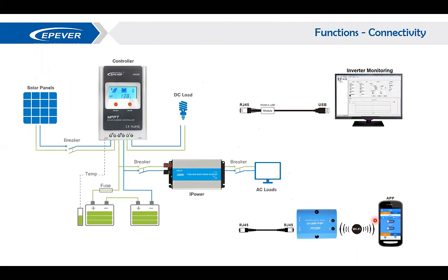So input voltage, let's say here on the input side, we have the input voltage, the input current, and the power and status. And at the output side, you will have the output voltage, output current, power status, and the device temperature. So what I already mentioned can all be monitored via the RS-485 port and within the software.